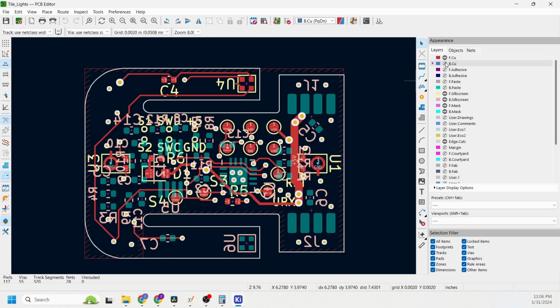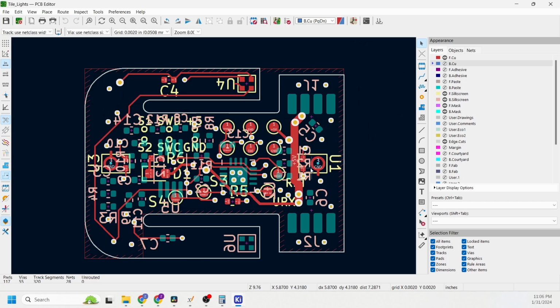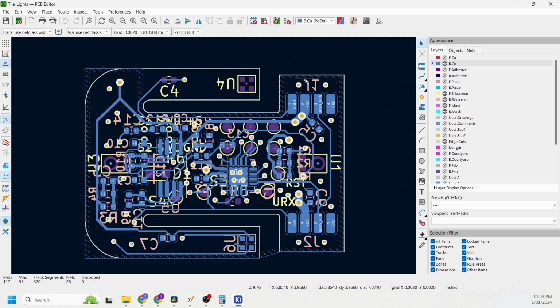The front side has the microphones, the debug LED, and the test points. Now this proved to be a bad idea, putting the connections on this side, because once I glued the circuit board onto a tile, I could no longer access any of these. The back side contains everything else. The pads for the ribbon cable, the processor, the op-amp, and nearly all of the passive components.